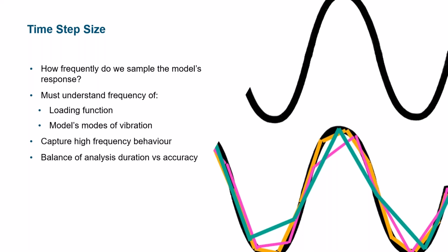solution. And again, if your time step size is too large, the loading events might be missed, and the components of the structure's response with high frequency may be misinterpreted, or you might get inaccurate results due to that. And again, if the time step size is too small, the analysis is going to take too long. The results files will be large and perhaps more difficult to work with.